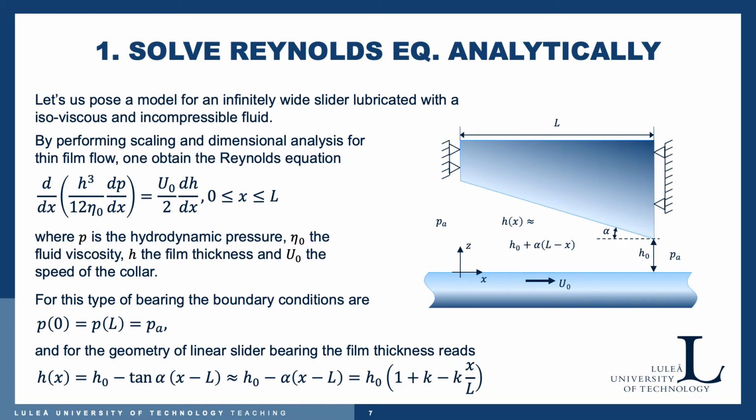So now we really can ascertain that we have the quantity levels assured, so we will know what the pressure would be for an exact situation of this bearing where we define L, U, eta naught and K, and actually also the film thickness, the minimum film thickness at the trailing edge H naught.